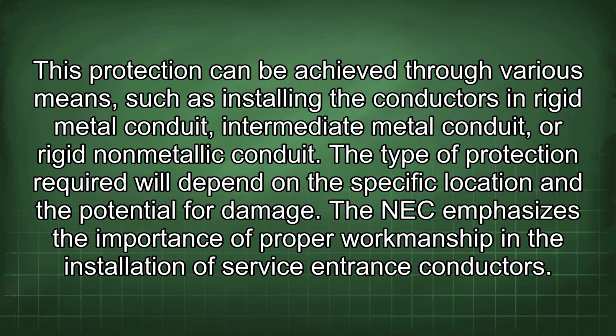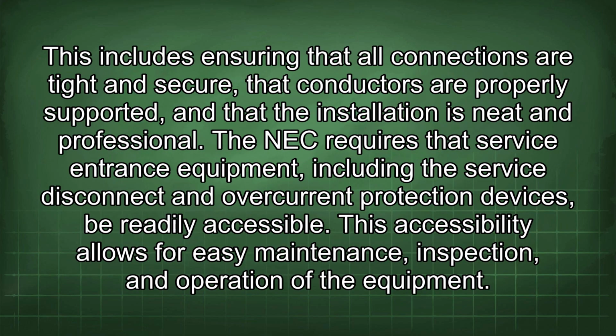The NEC emphasizes the importance of proper workmanship in the installation of service entrance conductors. This includes ensuring that all connections are tight and secure, that conductors are properly supported, and that the installation is neat and professional. The NEC requires that service entrance equipment, including the service disconnect and overcurrent protection devices, be readily accessible. This accessibility allows for easy maintenance, inspection, and operation of the equipment.